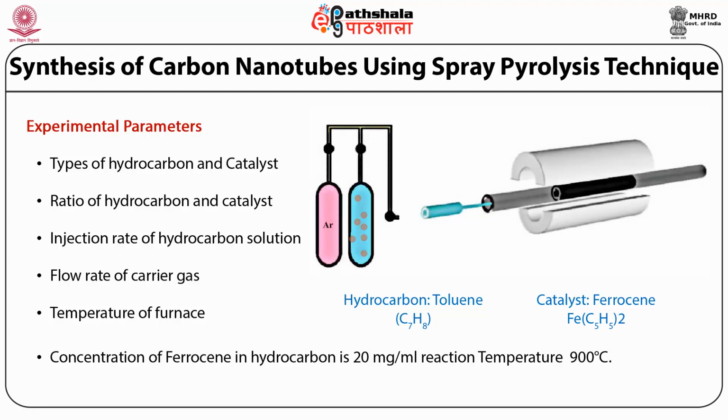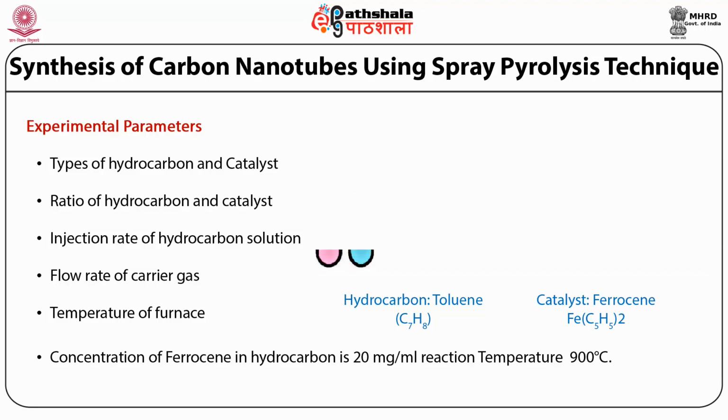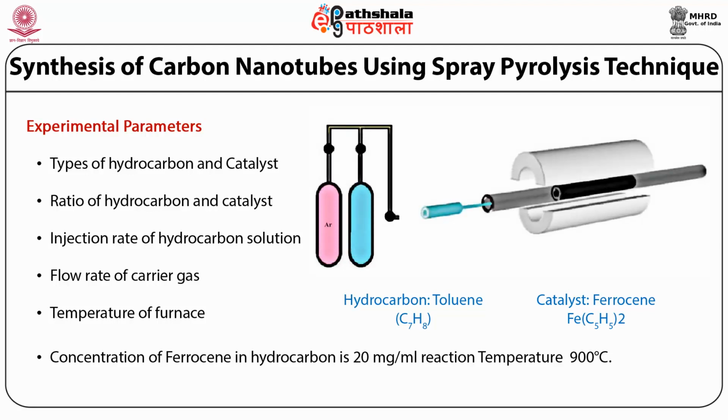The aligned nanotube that forms uniform nanoporous cylindrical membrane walls are synthesized from sprayed ferrocene derived iron catalyst. The nanotube grown in radial direction on the wall of removable silica tube template, leading to formation of freestanding and continuous hollow cylinder carbon tube. This provides a monolithic nanotube macrotube formation.